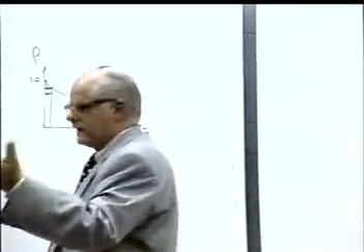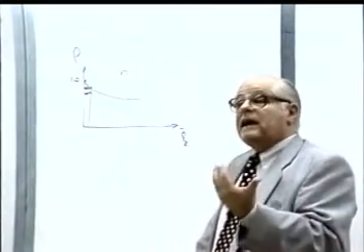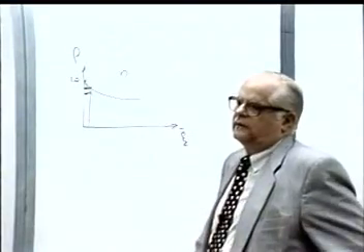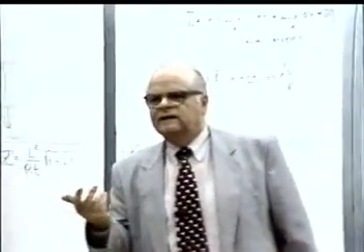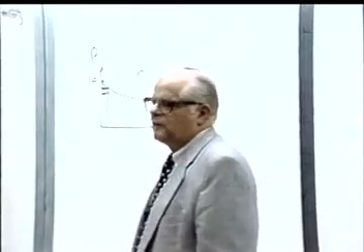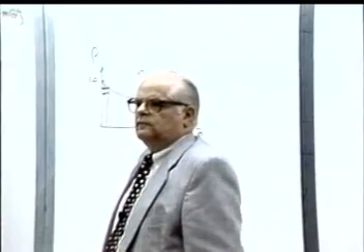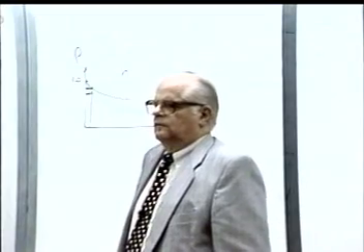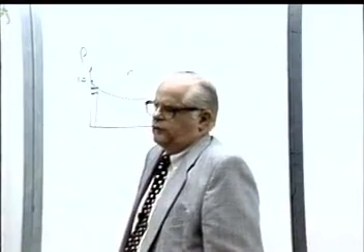Why? The Xi bar, in general, what I have seen is an order of magnitude smaller, not a little bit smaller, than on metallic shells. Metallic shells will always have imperfections of the order of the wall thickness, and the imperfection that you measure on a composite shell will always be less than 10%. So it is an order of magnitude. But this has a very interesting theoretical implication, because it means that for composite shells we can categorically say that asymptotic analysis performs better. Yes, it should.